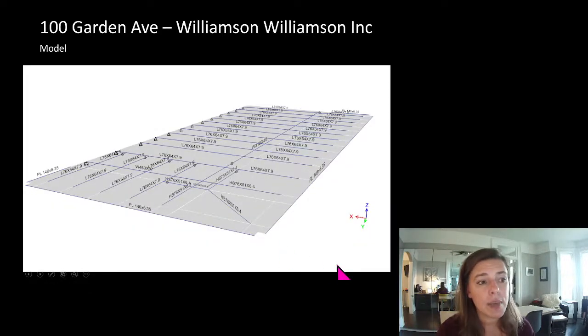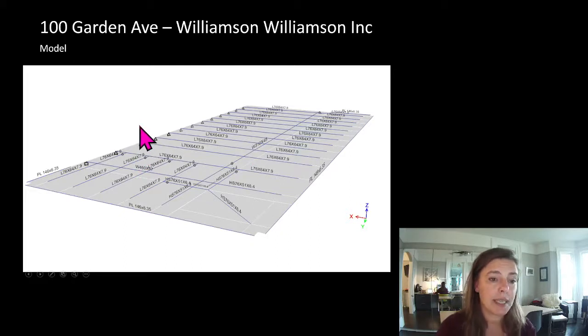So here's an image of my model. So here we have plate steel spanning between different supports. And what I did here was I made these angles that could be welded to this plate steel, and this would have an upturn on it. And these would cantilever. They would connect to the existing building at the existing building steel and come back and connect to the existing building back at the wall of the recessed part of the building.